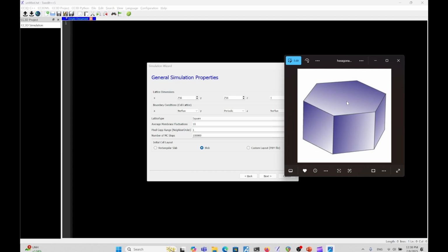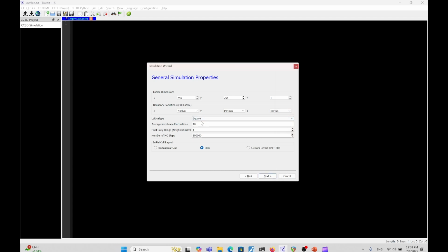The hexagonal prism has different symmetry in the XY plane compared to the Z direction. So this might not be suitable for 3-dimensional simulations unless your XY dynamics is inherently different from your Z dynamics, for example, in an epithelium. So in general, we recommend using square lattice unless in 2 dimensions you are trying to avoid lattice spinning.